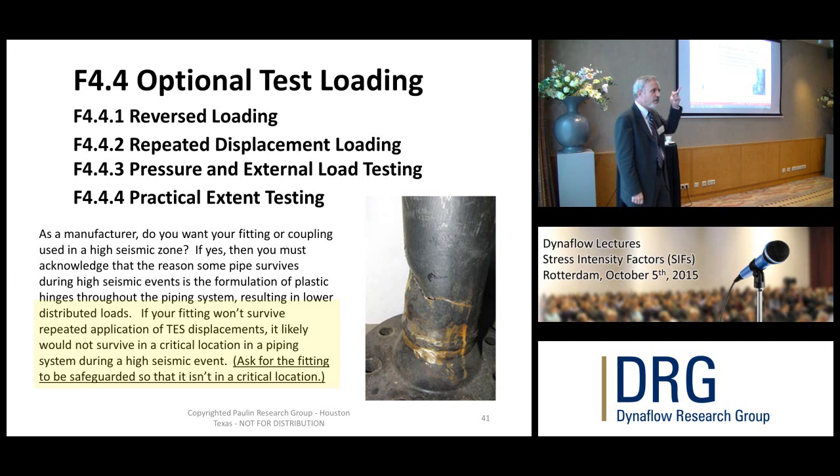And you've got to think about it. If you get something that's pressure sensitive, what you do is you make sure it doesn't suffer bending. Because the problem in an earthquake is that things shake a lot. At high points where there's high bending, that's where it plastically deforms. So you don't let these things get exposed to high sustained bending moments. You put them in a straight piece of pipe, but with supports all over the place. No problem. So that's the safeguard recommendation, hopefully. Whether the words come out that well or not, I don't know.